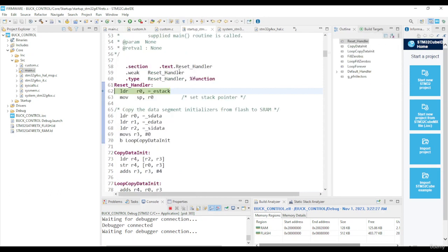And just keep in mind, it's not modifying the duty cycle directly as a result of the sensed output voltage. It takes that, generates a reference current value from the output voltage, and then the reference current value is what's used to actually modify the duty cycle directly. So it's almost like indirect control, if you will, not direct control.